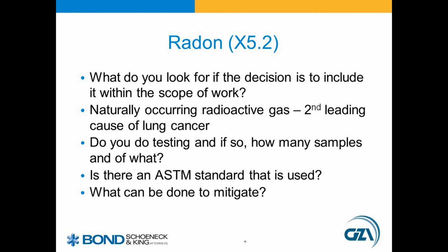Another pressing issue to investigate is the presence of radon, which is the second leading cause of lung cancer in the United States. Radon is a radioactive gas that's typically associated with shallow bedrock. It comes up from the bedrock and infiltrates into the building structure. It's easy to test for, and much like mold, there are at-home do-it-yourself methods to test for it, which involve hanging essentially a piece of foam in the breathing zone of each level of the building, and then sending that foam off to a lab for analysis.